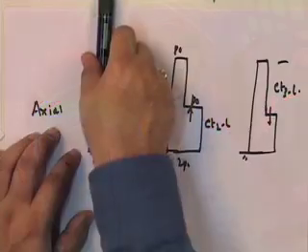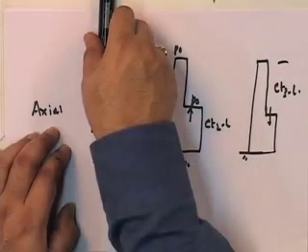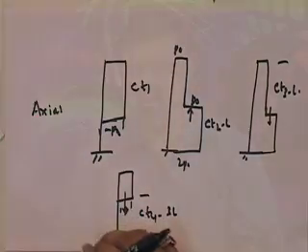So what we got over here, I'm getting for any instant of time, x and t, of course for various components, and c is square root of E upon rho, a longitudinal wave. It's actually traveling along the axis and then going back along the axis, coming back, going back. This is a wave propagation problem. I'm not going to be talking about wave propagation in this course. It will be taken up in a later course, but the essence is that this beauty that you see comes from the series solution. So that's all I have to say.